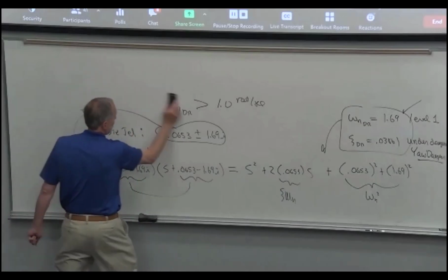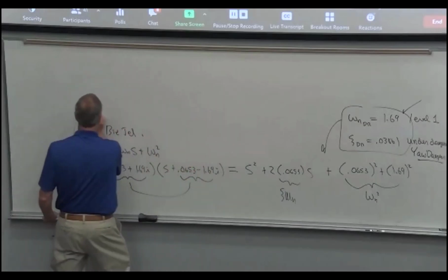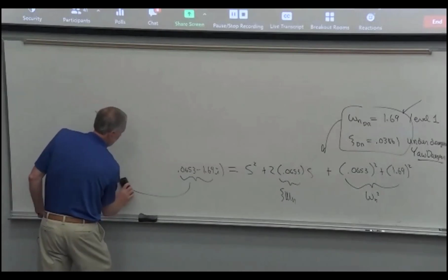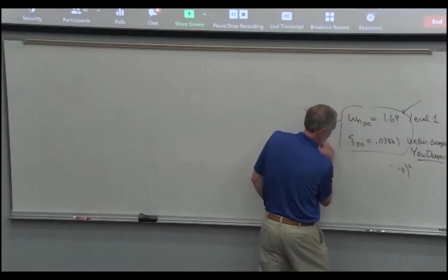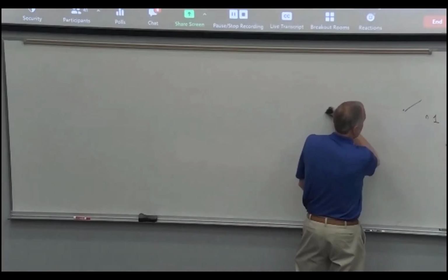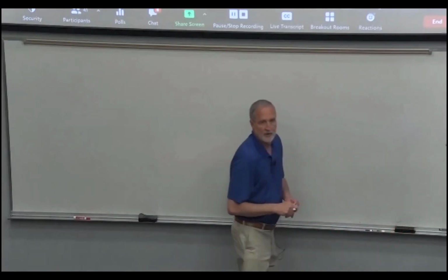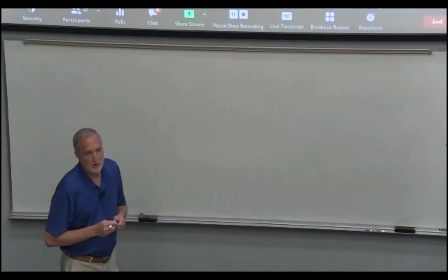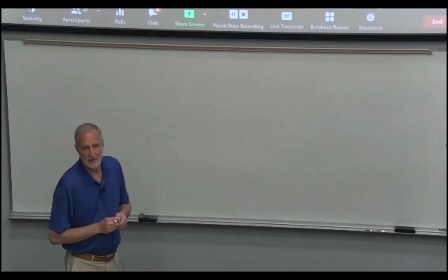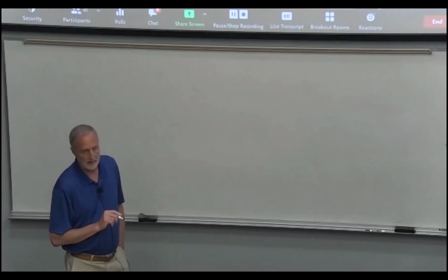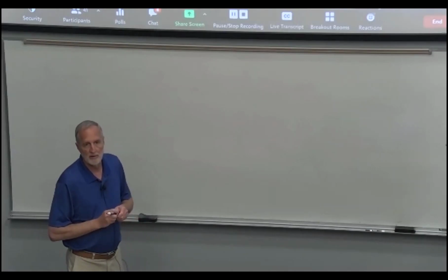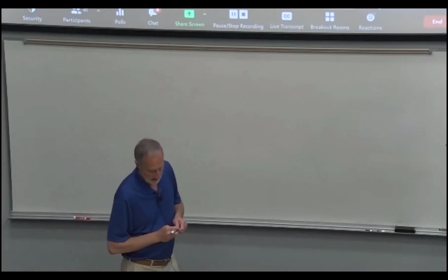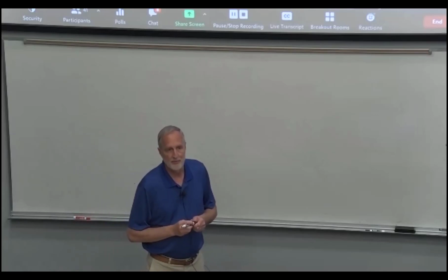And so the next step, once you've done the preliminary design and calculations, like we've done in this class for our airplane, then you build a wind tunnel model and test it in wind tunnels. Makes sense. And then you could do what we did. We imported it into X-Plane and essentially flight tested it in simulation. So that's typically done to test out the dynamics. And in a flight simulator, they would bring pilots in and run their simulated model to see how well the airplane flies. And then eventually you build a prototype and test it.